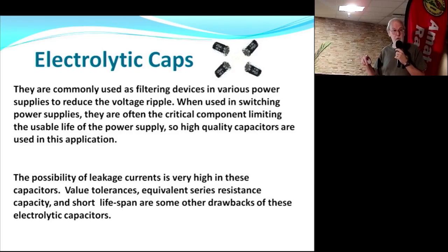And sometimes it's very dramatic when you first power it up, which is why they usually recommend that if you have an older rig, you put it on a variac or transformer and bring it up really slow, let the tubes and those electrolytic capacitors sort of get back in the game. Otherwise, you're going to cause yourself some problems. The leakage current on even a good electrolytic is fairly high. Relatively speaking, it's the highest in all the families. So that's sort of how they self-discharge.